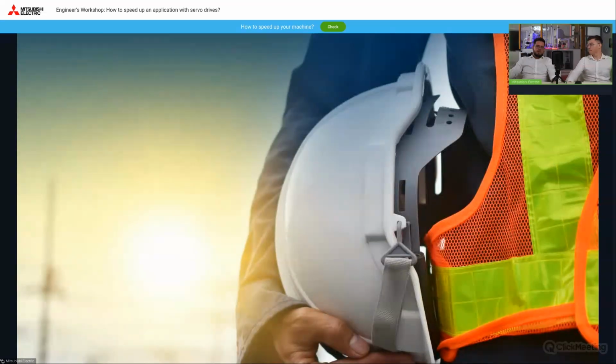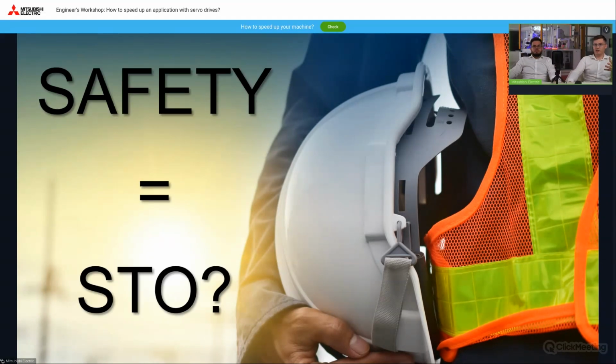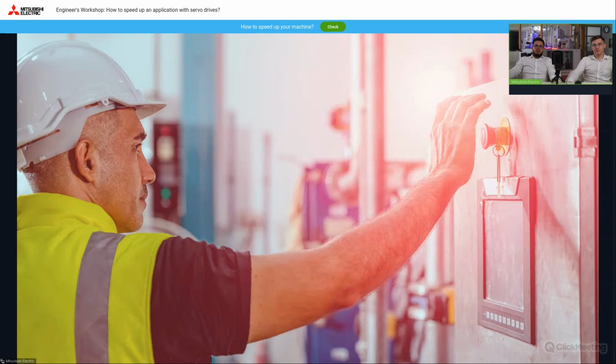Another extremely important thing is safe stops. So, STO? Not quite. What do you mean? Isn't it just about making the machine safe? Yes, it is an important aspect, but what also matters is how long the machine takes to be restored to operation after being put into a safe state. We say this because after typical STO or even SS1, it takes a while for the drives to resume operation. By using advanced safety functions that don't remove voltage from the amplifier end stage, it's possible to reduce downtime and start immediately just after the safety system has been set up.